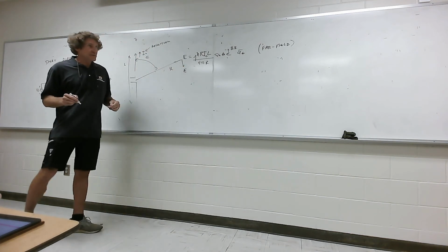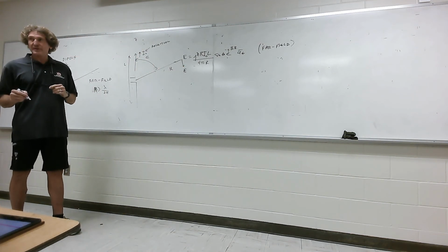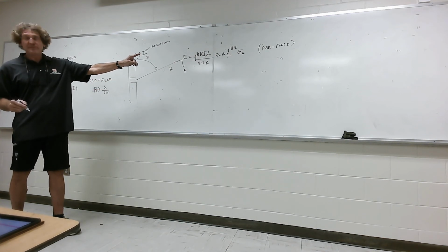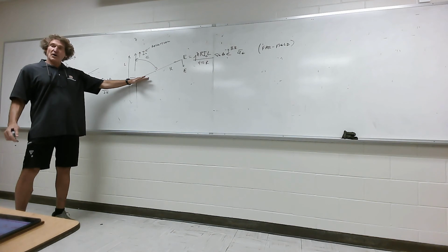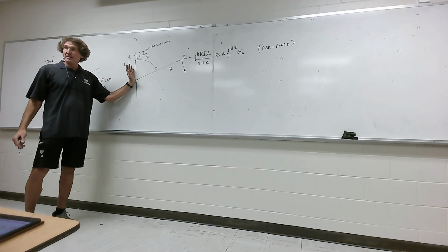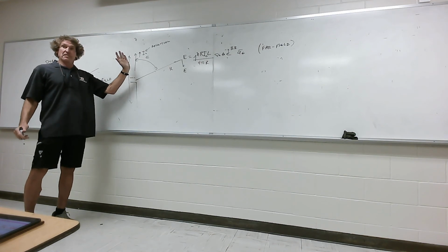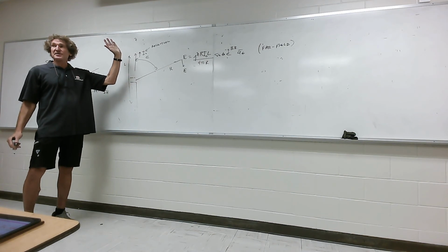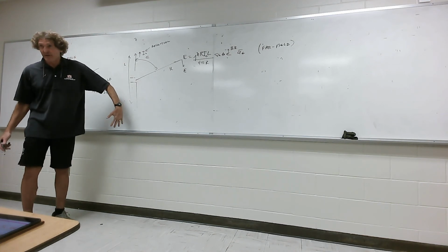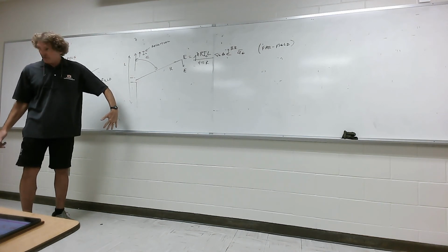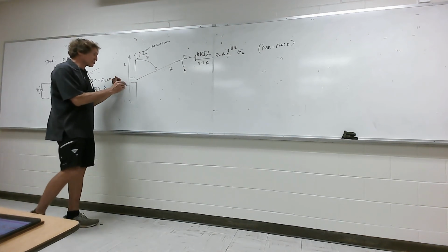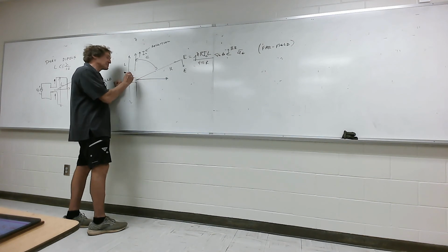Now, in magnitude, I got one other point about this, because I'm not going to have enough time to do everything I want. When I look at this, it varies as the sine. So how much electric field radiates straight up? Well, what's the angle straight up? 0. What's the sine of 0? 0. Nothing goes straight up. How about straight down? 0 as well, right? Where's the maximum value? Right, it's called broadside. It radiates maximum there.